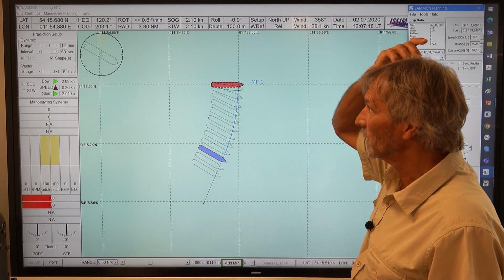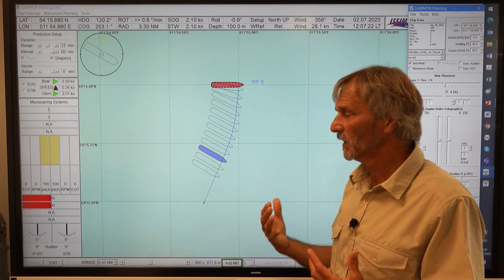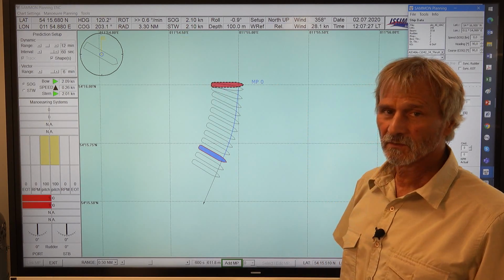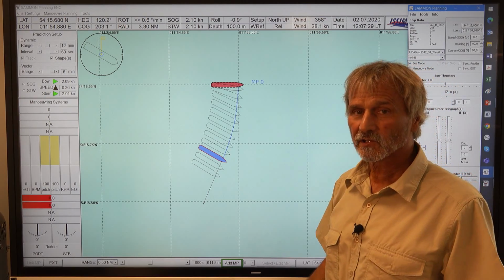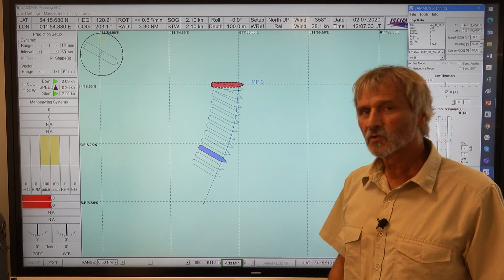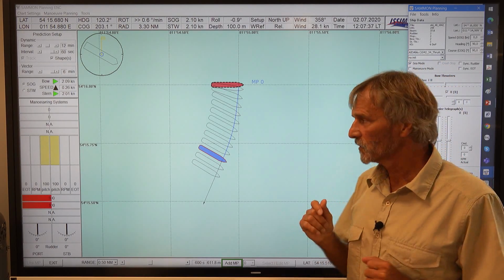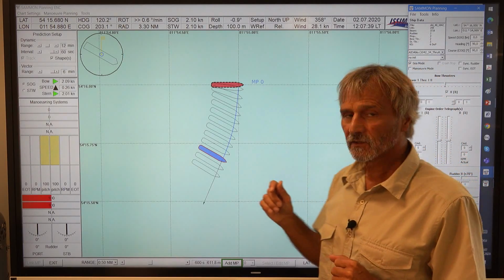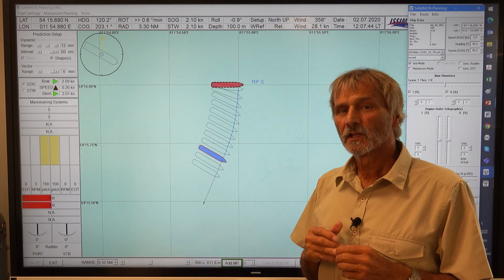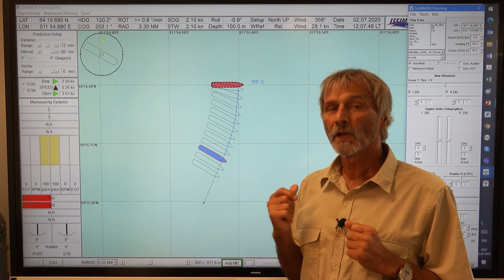And the drift speed decrease we can achieve is 2.10 knots. So we are a little bit slower than the 2.25, 2.4 which we had without the thruster. By the way, I should also mention that these 2.2 or 2.3 knots are about 7 to 8% of the wind speed.